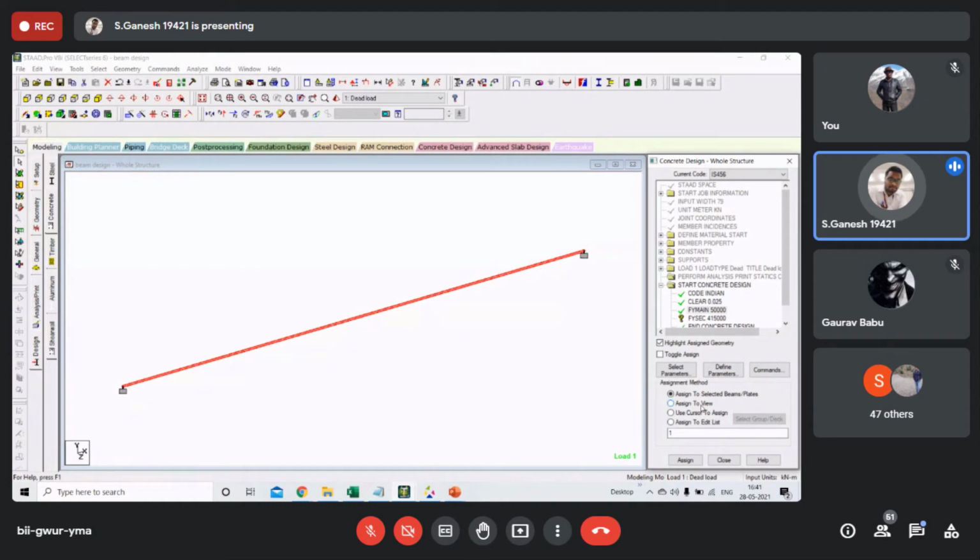So when you have a beam element, select the particular beam, give the particular inputs. If you have a column, then select the particular inputs for the column. For example, for beams you have some M25 grade to be poured, or for columns from 5th level to 7th level you have a higher grade, M30 or M35, to be poured. So you need to select that accordingly with the section view or grouping method. Then you select the parameters assigned to that. Since here is 1 parameter, I'm just selecting it and giving all this part. Right. So this is done.